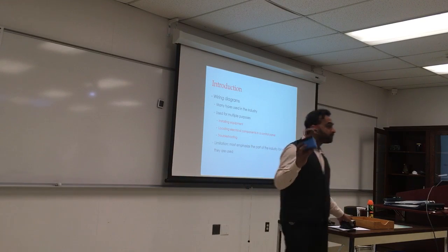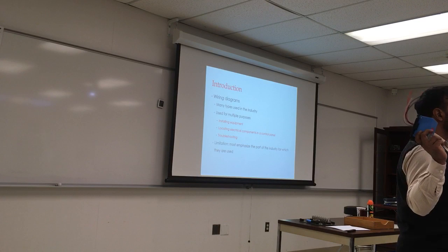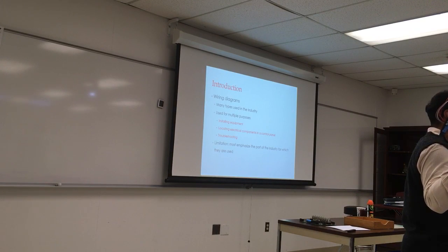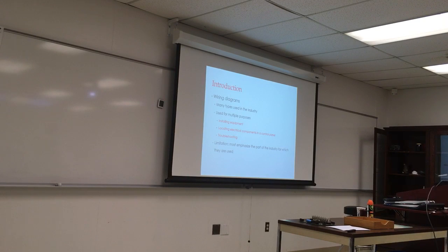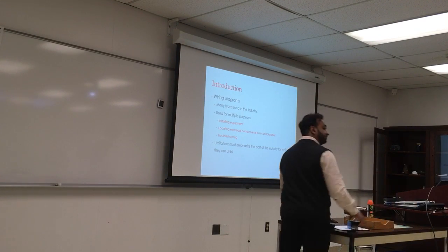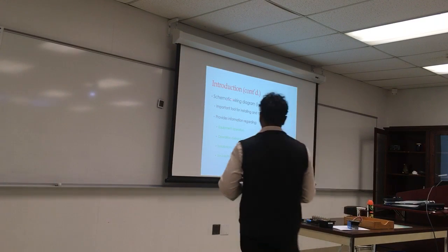For these two primary controls, the limit is supposed to be energized. The relay here is normally open, so you have to make it normally closed. So you have to energize the limit. The limit by default is normally closed, so I have to energize the limit. I will supply power to the outline and also to the limit. You don't have to remember this for now. We'll go over it again a lot.